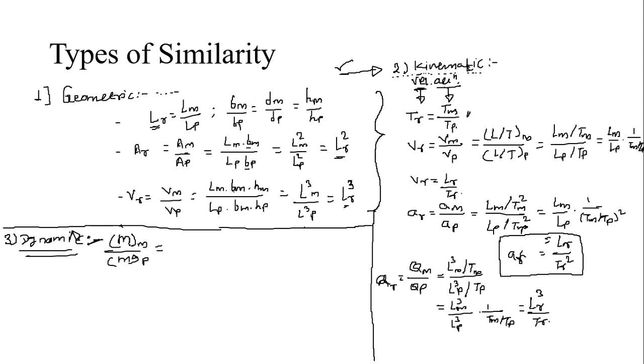We have summarized here that momentum, means the change of momentum will be due to the various forces acting on it. It means that if you are going for the various forces, then we can write here the forces as viscous force is there, plus gravity force is there, then elastic force is there, then surface tension force is there, etc., etc. plus, in the model, at a particular point, whatever flow is happening